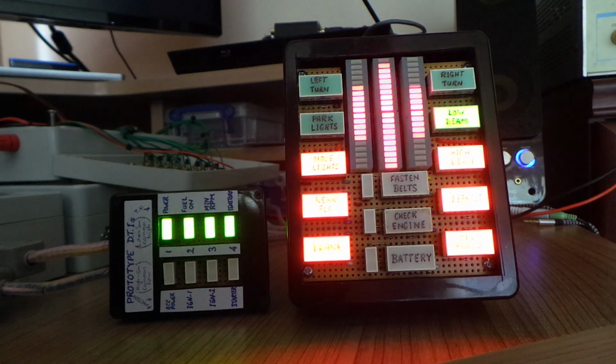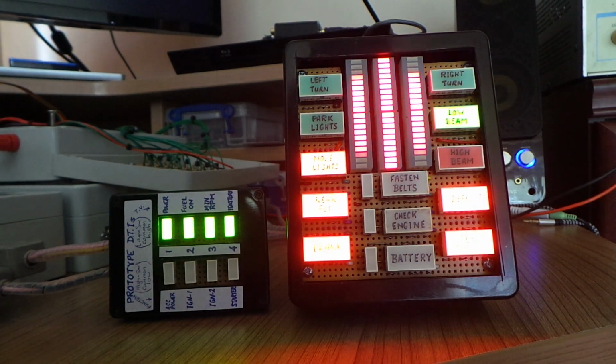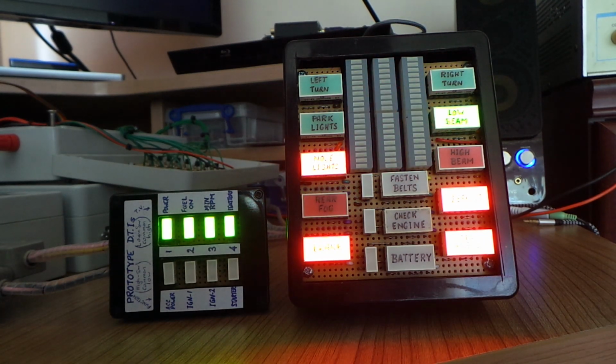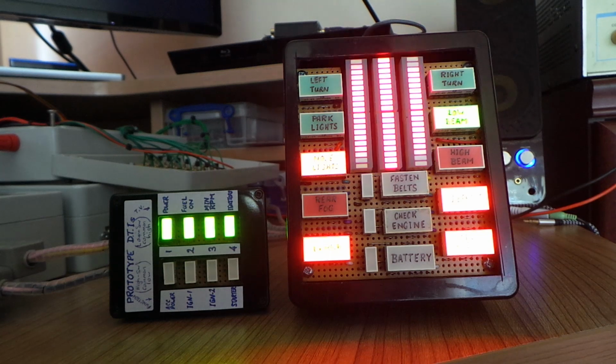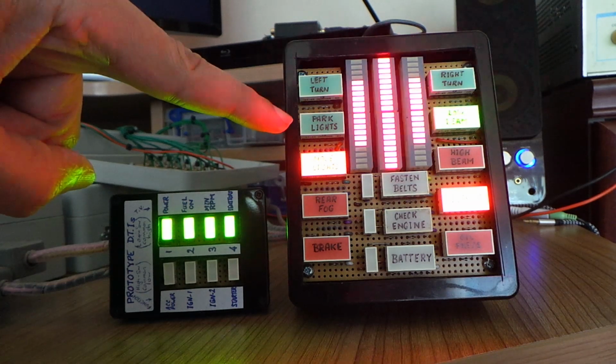Now the side indicators, at the moment they are in the normal display mode. There is an alternate display mode for the side indicators, and to demonstrate this, let's just switch off some of them. So let's switch off the high beam indicator. Let's switch off the rear fog lights. Let's switch off the brake and oil pressure inputs, so we just leave 3 of them on. Now in this normal display mode for the side indicators, the indicators are illuminated when the corresponding input is active and extinguished when the corresponding input is inactive.